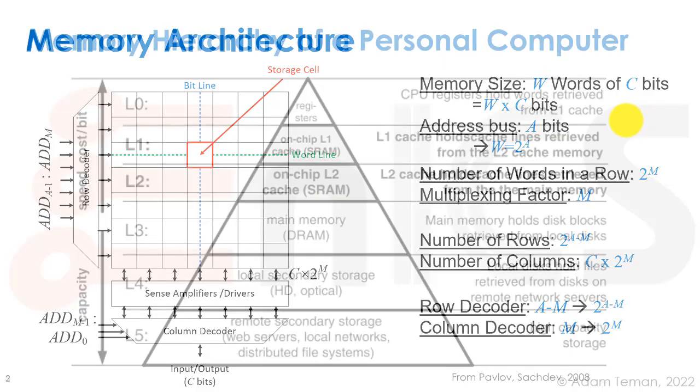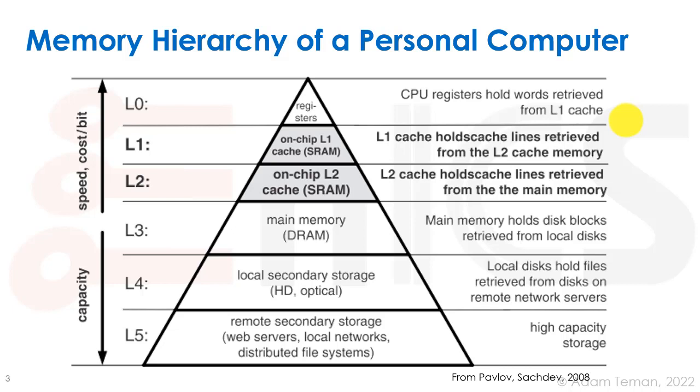To answer that, let's look at the memory hierarchy of a personal computer. Really at the top we have our CPU or our computational unit, whatever it is, and closest to the top of this tight pyramid we have the fastest memory, the closest to the actual computational unit, which means we get the highest speed. But unfortunately it usually means the cost per bit also becomes much higher. And the pyramid is much shorter over here, which means we have a much lower density. The first things up here are going to be the registers, the flip-flops. I guess it could be latches or whatever, but they're really in pipe inside the data path, and that's going to be the most costly type of